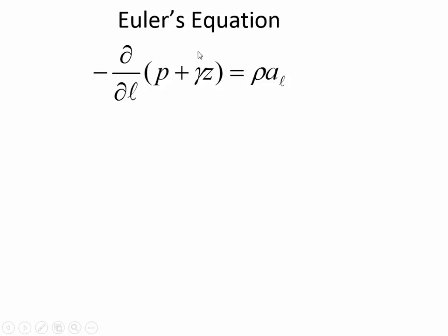And then inside of these brackets is what's affected by the fluid acceleration. It's the piezometric pressure. So P plus gamma Z is the expression we've seen before when we've talked about piezometric pressure. And what it means is that the fluid may have its pressure changed as a result of acceleration, or it could be Z, which is the elevation of fluid, or its position.